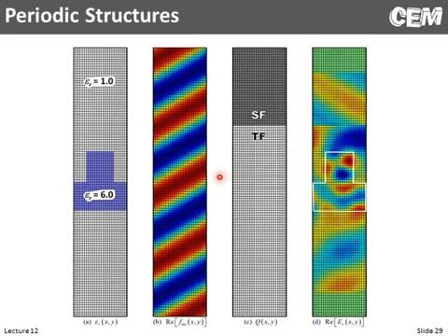In this class, we're mostly going to be modeling periodic structures, and our grids are going to look very similar to this. We are going to have our device in the middle, and there's going to be some space between the device and the PML. Our source fields are going to look very much like this. We're going to be injecting the plane wave in air, dielectric constant of 1. So in this array, we're essentially having a dielectric constant of 1 everywhere, and what would our incident wave look like if calculated everywhere? So that's our source field.